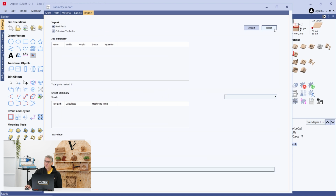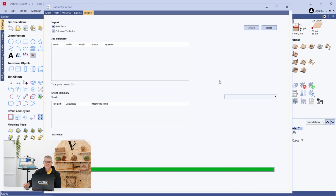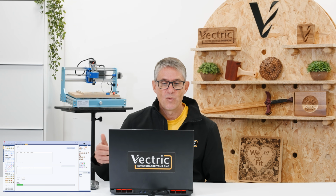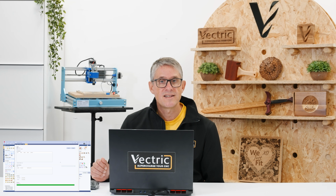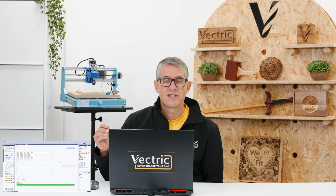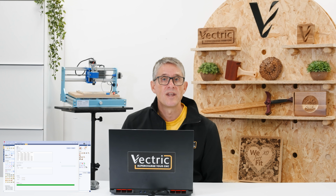Once we've done all that, we can simply decide whether we're going to nest and calculate the toolpaths all at once. Let's just hit the big go button, right? So now what's happening is that we are starting to bring in all those parts according to that part list. We're finding the best way to fit them into the sheets of material that were in our template. Once they're all in, we can then look at the toolpaths that are inside the template and start applying those toolpaths to all the layered information that was emerging from the DXF files.